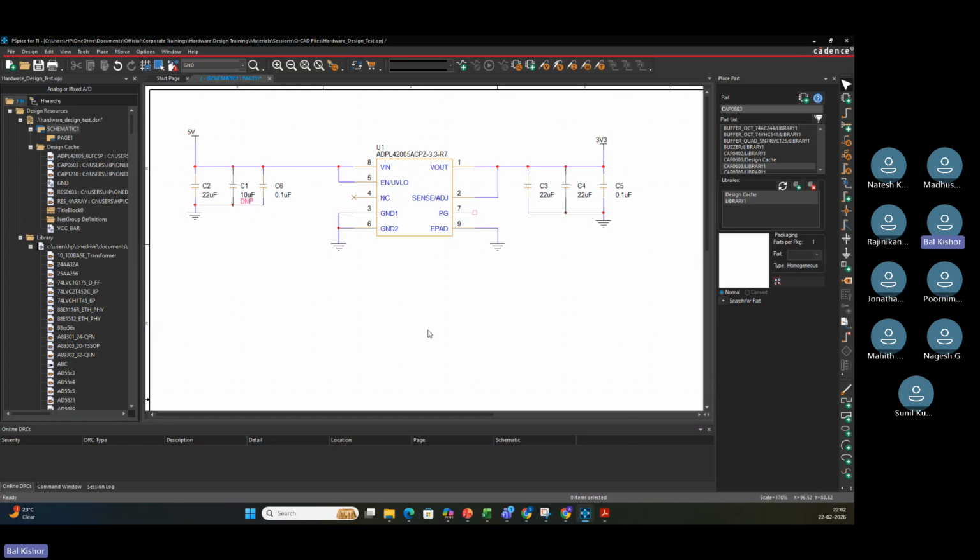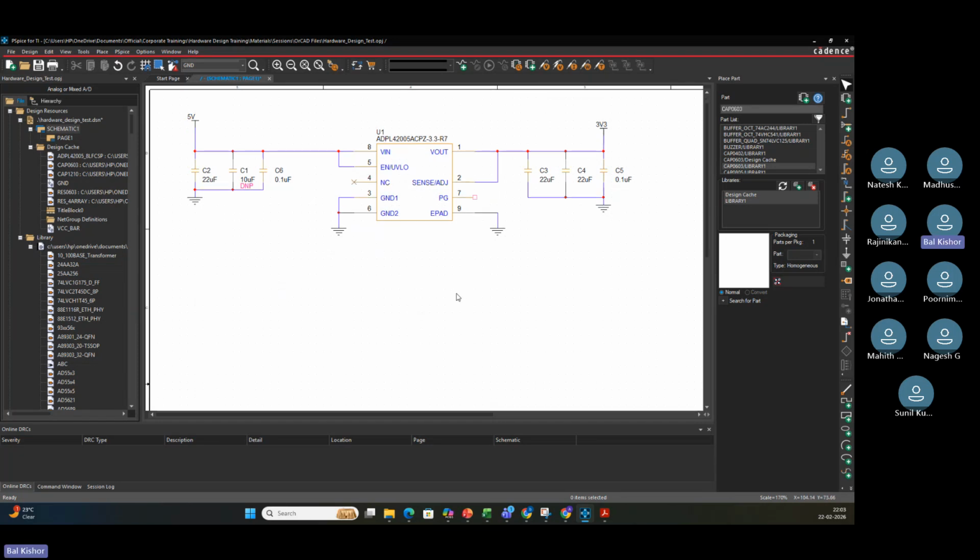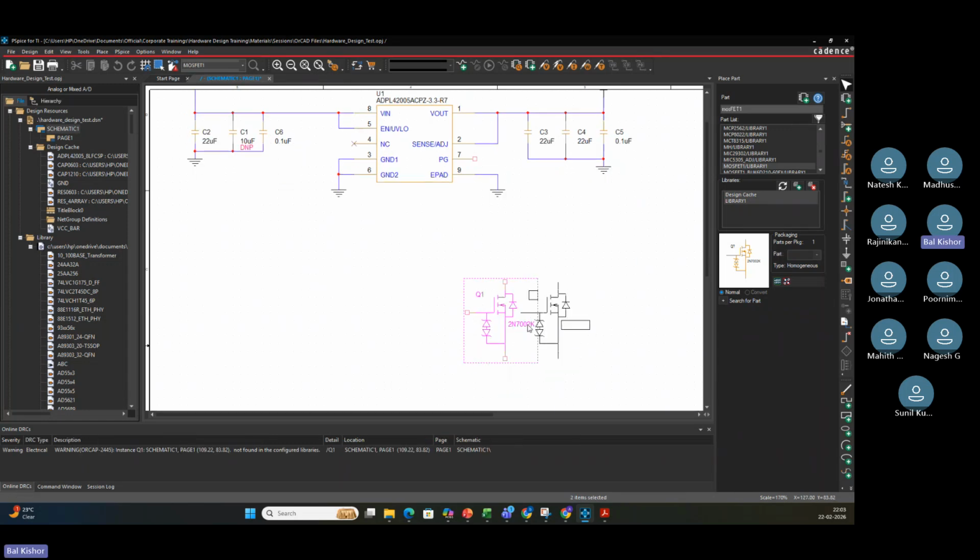All right. While creating this circuit, we will utilize this PG logic level, let's say 5-volt. Now I'll just create a simple circuit and ask you guys to create it. Let us say I'll put a MOSFET, and then I'm going to drive it through a resistor. Let us put one resistor, 0603, and then one pull-up resistor also.